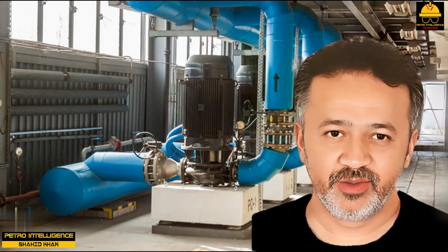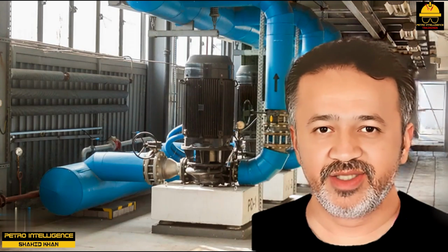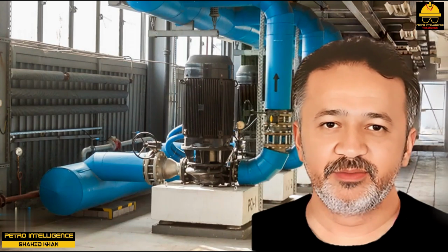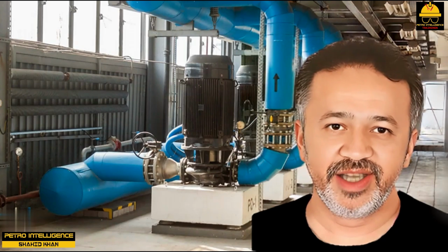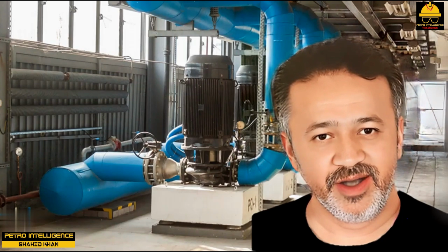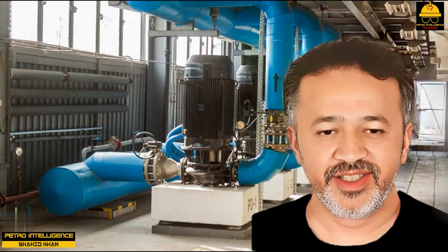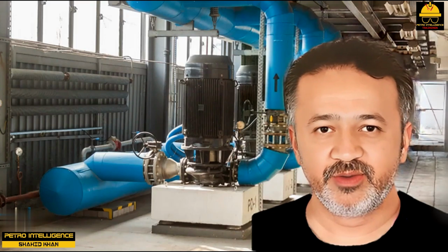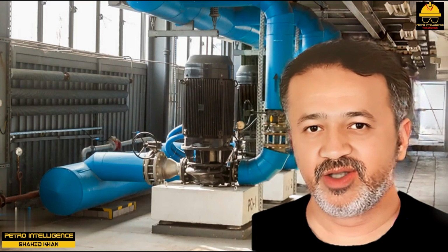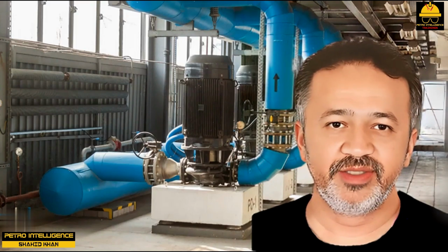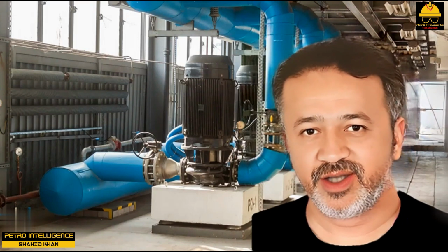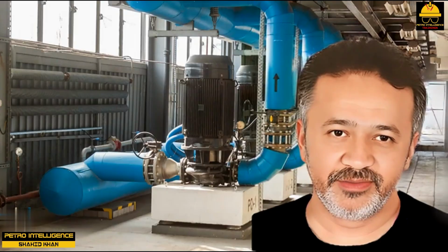It is possible to rewire a three-phase motor into a single-phase motor, and thus reduce its speed from 3,600 to 1,800 RPM. Then its power consumption would drop by a factor of 8. An engineer did this once at a refinery, which had a hugely oversized sulfur plant incinerator air blower. For most projects, a more typical option would be to retrofit the motor for variable speed operation, using frequency control. However, not all motors are amenable to frequency control, which is a relatively expensive option. Feedback from clients that have retrofitted pump drivers with variable speed AC motors is often unfavorable.